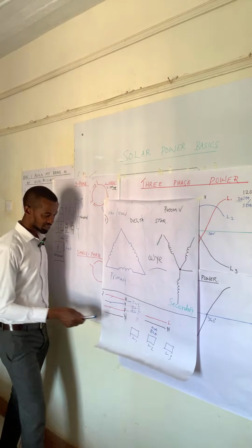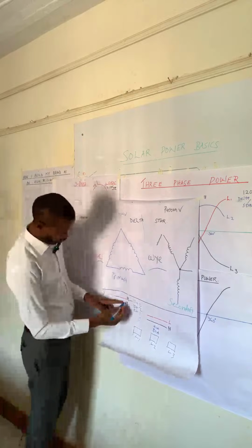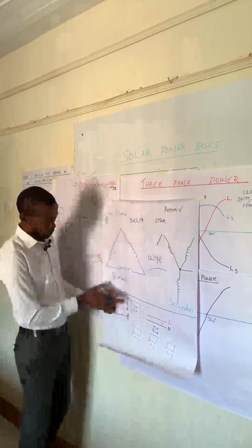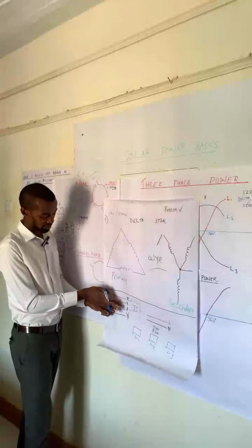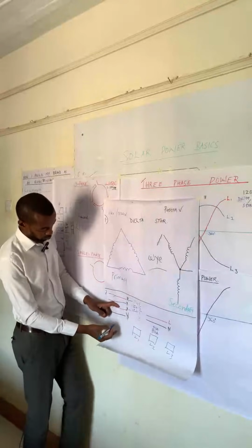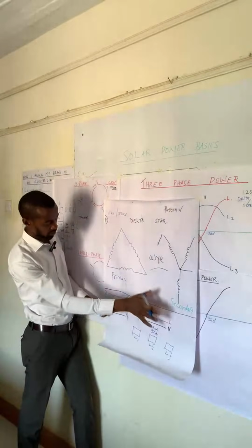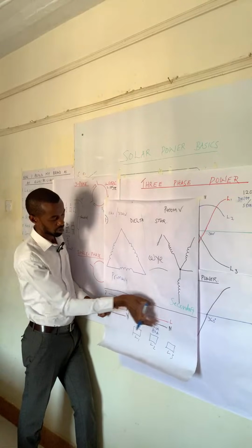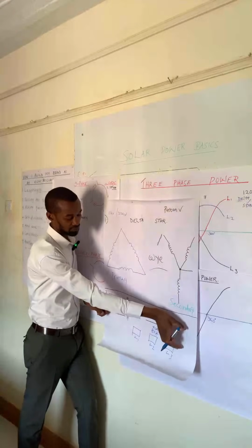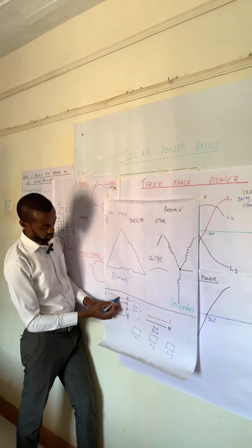Another thing is at the point where we have this three-phase power distribution, and this happens again in towns or in urban settlements, you find that there's a common transformer, this one, and then along the way, before this three-phase distribution gets to the three-phase customers, you find that there are single phase connections.